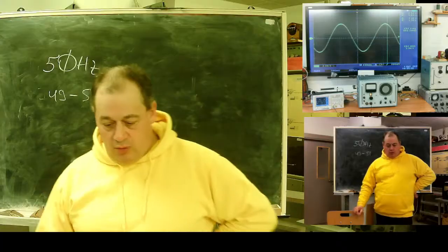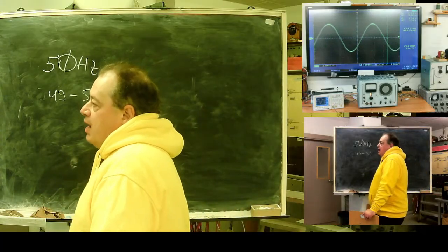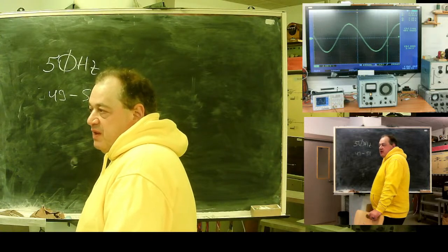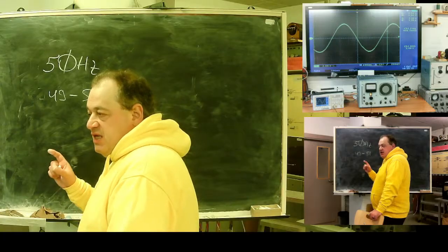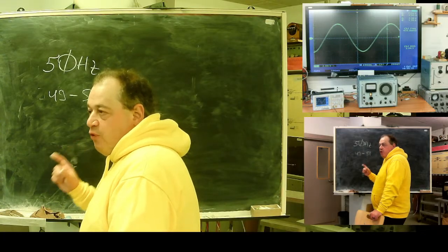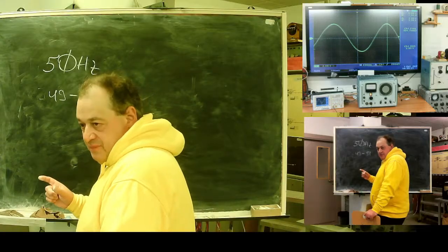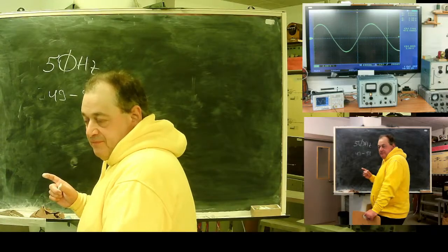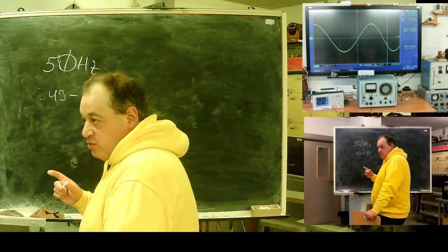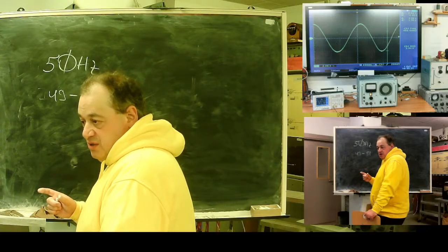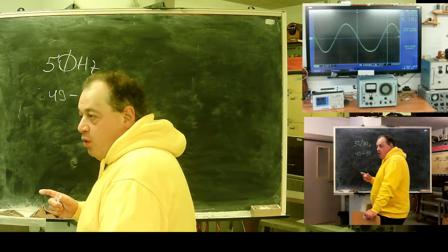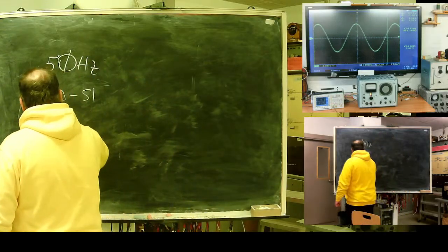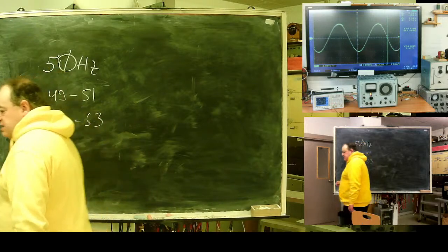Wait, I can tell one thing. Steam turbines have a setting. A steam turbine will perform an emergency stop if frequency exceeds 52 Hertz. It's a normal setting for emergency shutdown. Low will be somewhere at 48. So something like 48 to 53 is reasonable.